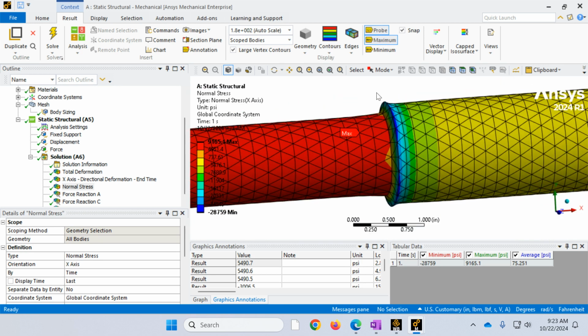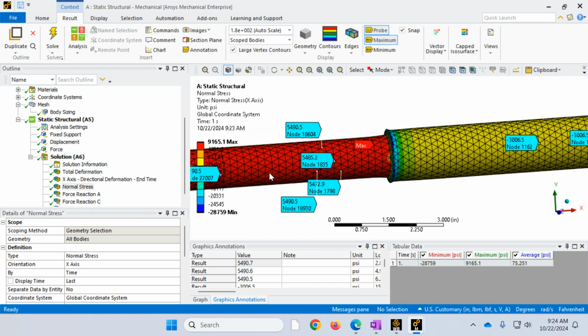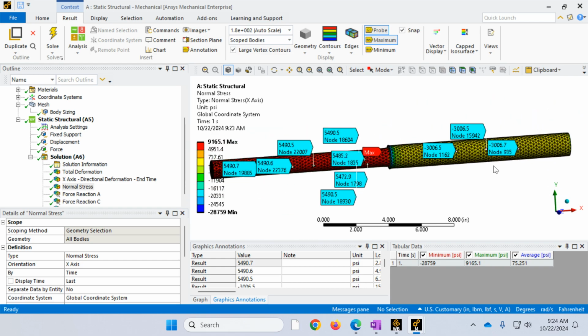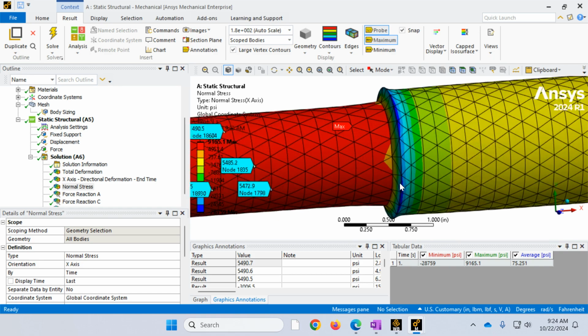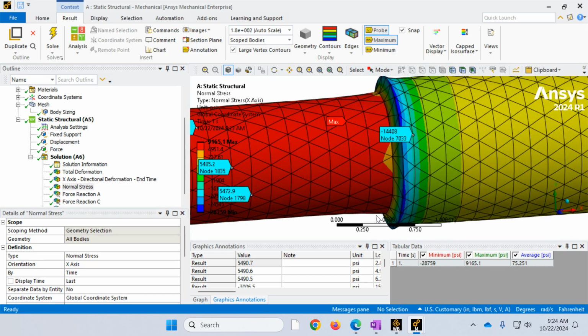So that's why when I'm using my probe to find the stress in the part, I was not going close to this part where there is the intersection of the pieces, but rather if you pick any point close to midpoint or away from any discontinuities, you should get the right answer. Likewise, if I come here, I'm getting like negative 14,000. Again, this is an error, and I can enhance the performance if I continue to use a finer mesh.